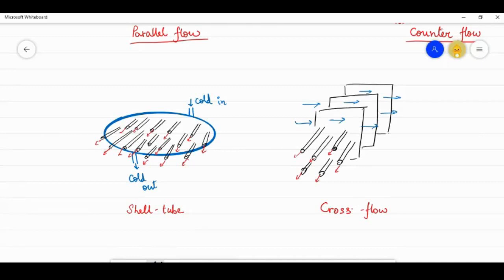exchangers. And in the case of air handling units or fan coil units, there are motorized fans present near the cross flow type heat exchanger in order to enhance the transfer of heat. This is how the fan coil units or air handling units increase the rate of heat transfer from within the building to the chiller water.